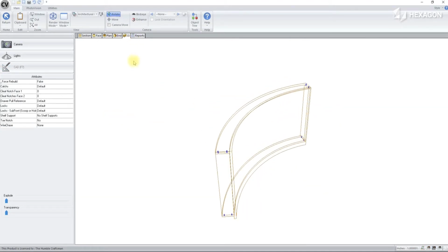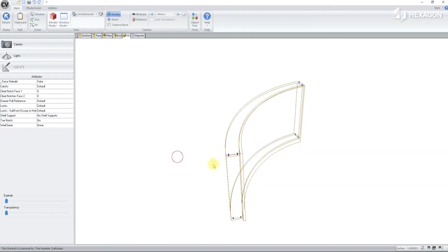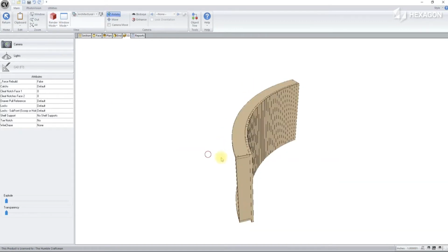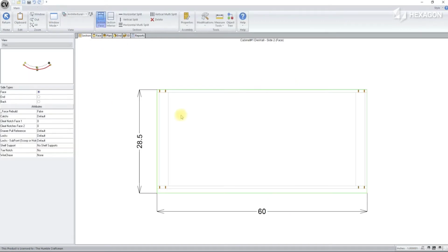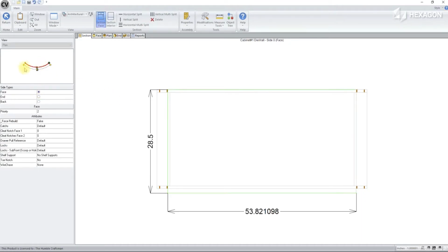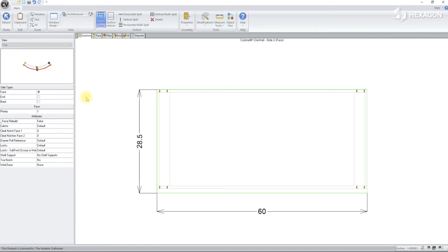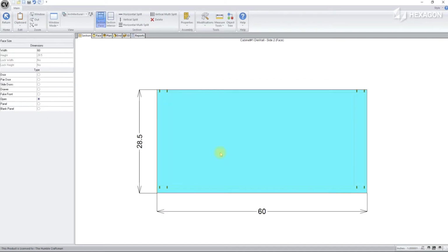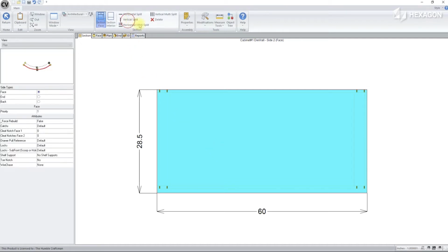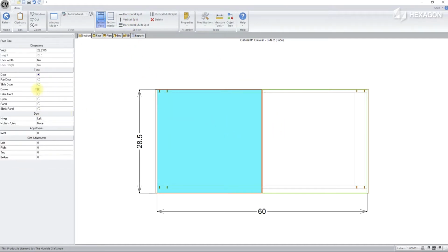So we have a top and bottom plate, we have our two ends, and we have a front and a back. But for Diewalls, it works best if we do two fronts. So we're going to go ahead and make that inside curve a second face. We'll go ahead and make sure that the ends are unfinished so that they can receive any notches or wire chase openings like the partitions, which are the wall studs.